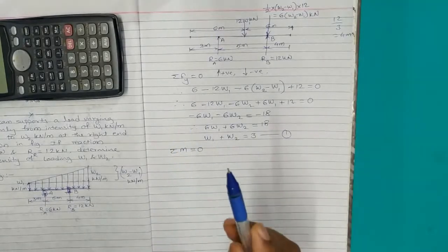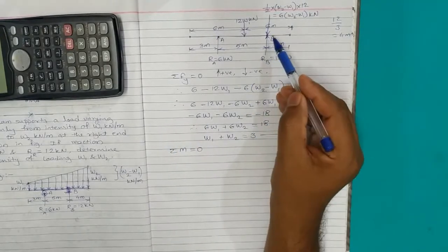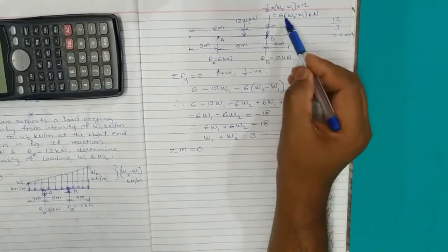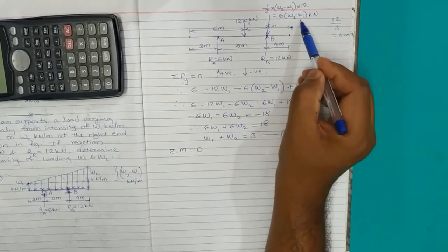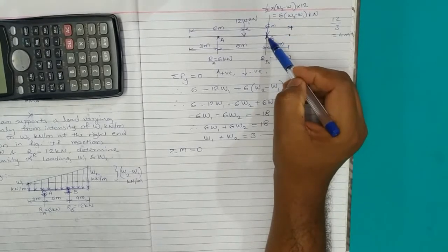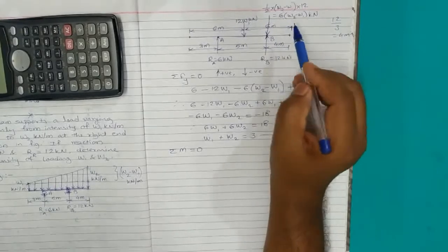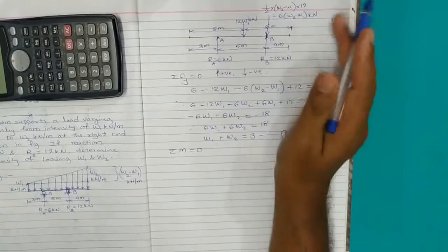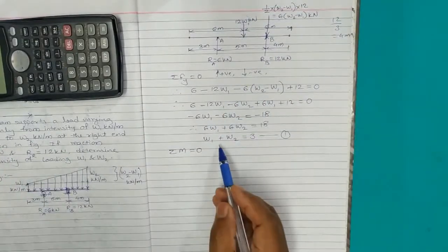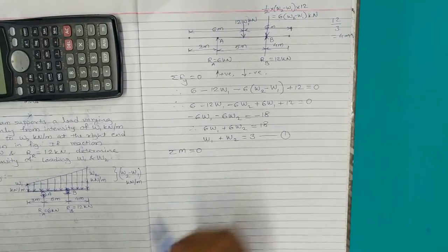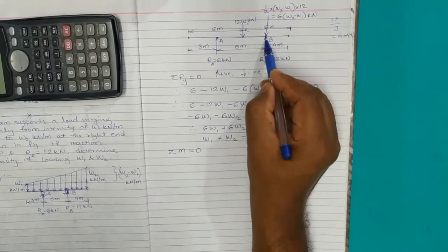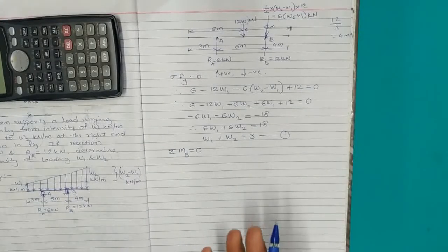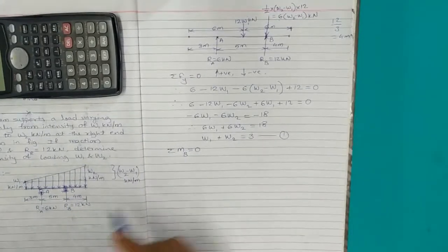But we have one advantage if we apply moment about point B. If we apply moment about point B, the load 6W2 minus W1 is applied at point B itself, so its moment is going to be 0. So in our equation, only W1 unknown will be there. W2 will not be there in the equation, so W1 will get solved and we can substitute it over here in the equation. Let's see. Let's apply condition of moment about point B. Anyhow, point B is one hinge also, hinge supported point.